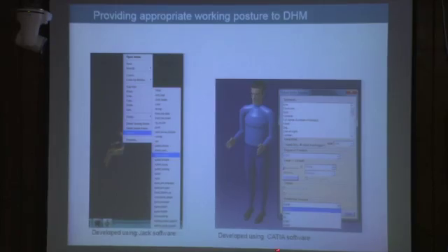From other software, say CATIA software, after creating the digital human model, you can manipulate individual body segments. You can change the motion of an individual body segment based on this. These are the segment lists, and then you can change the degree of freedom here, whether this is flexion, extension, abduction, adduction or rotation, and accordingly you can change the angle also. This is for different body segments.